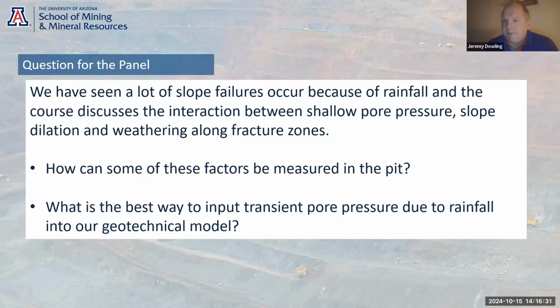And a really good practice is to have a set of hydrogeologic cross sections that include the piezometric data, but also all the secondary observational data about water as well. So the locations of wet blast holes and the locations of observed seasonal or permanent seeps in the pit slopes, for example, and the location of flowing horizontal drains.